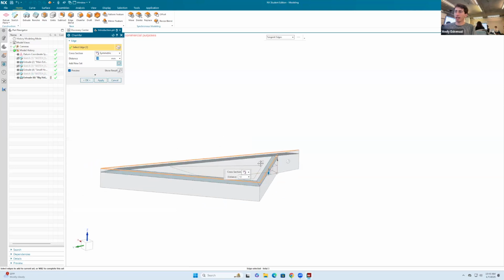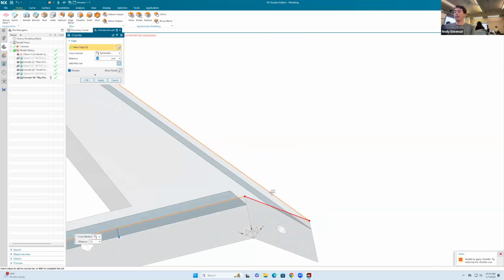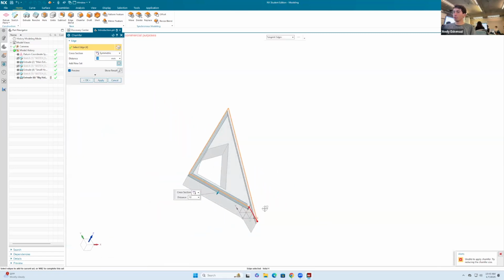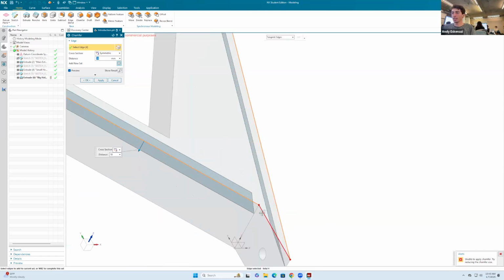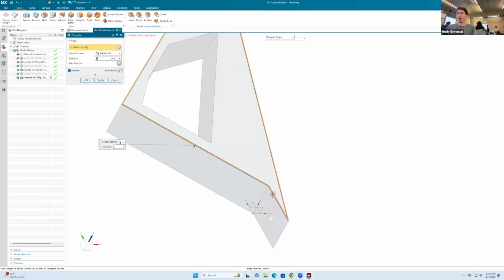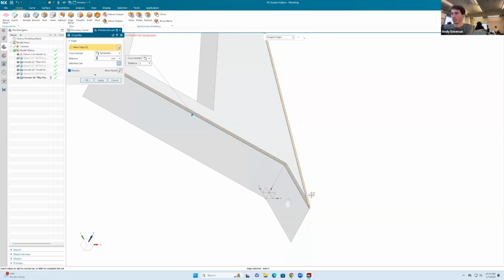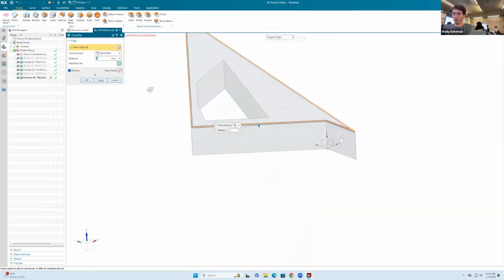And see how it makes like a nice... actually it doesn't, sometimes, as you can see, unable to create chamfer on this one. It makes sense, but that is too thin of a space. Now, if I were to reduce the chamfer to 1 millimeter in there, then it's able to create that chamfer in that particular angle. So you might be constrained. I can try, for instance, 2. Yeah, so 2 is within the limit of what it can do.